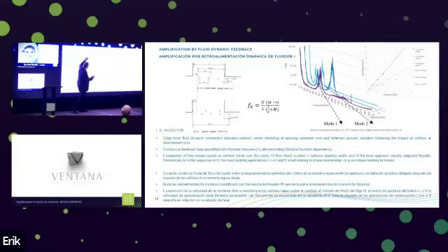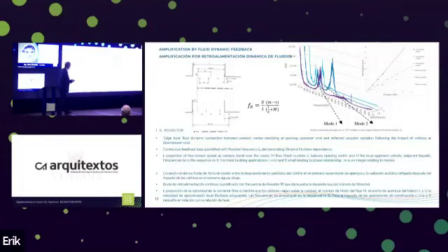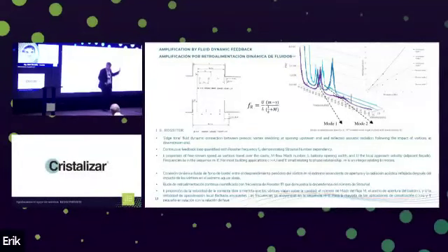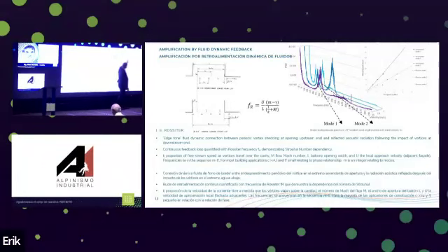And we get the same thing happen again, and we get this loop established, which can actually be defined through this Rossiter frequency function. Now, those same spectra I showed earlier, if they're laid out against velocity in the third axis, you can see these modes appearing, these alignments of the peaks. And what that's demonstrating in fluid mechanics wind engineering talk is a Strouhal number dependency. What that means is, as the wind speed increases, so does the frequency of this excitation.